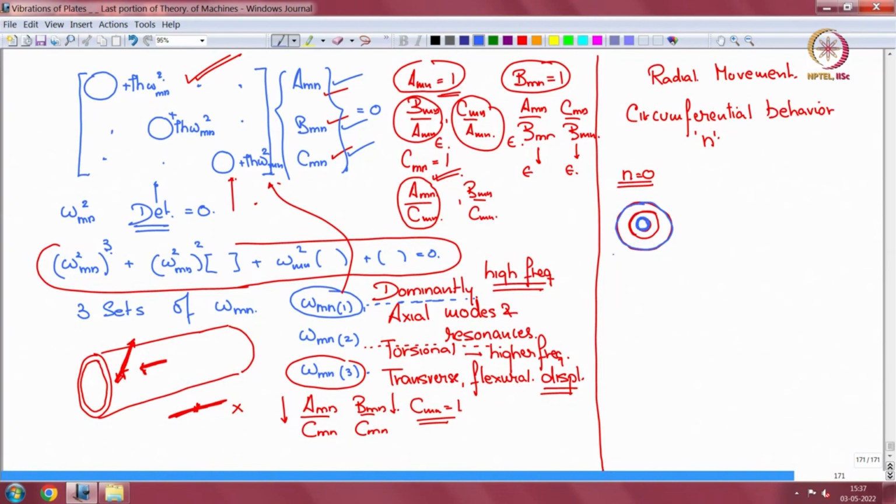So, there is a lot of stretching as we call it. The shell stretches and that is how you get this, which is like a breathing, called the breathing mode. Like you breathe and your chest cavity uniformly expands. And there is hardly any bending, no bending. The shell element is not bending. There is no bending happening.